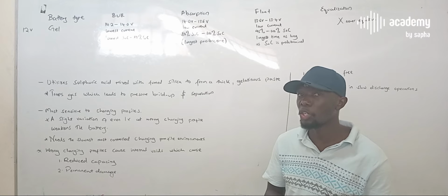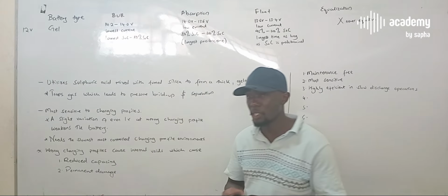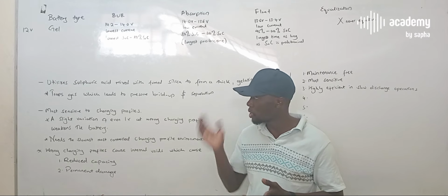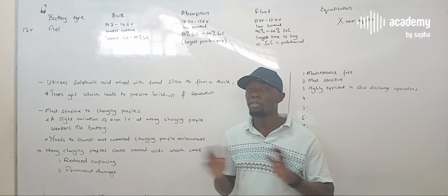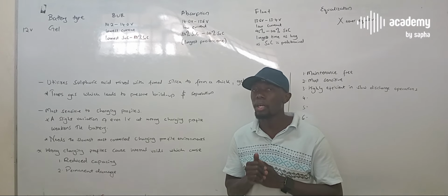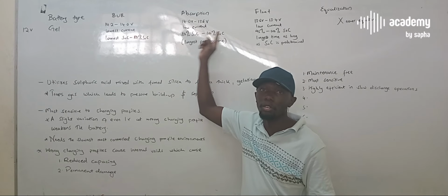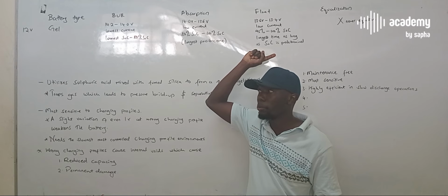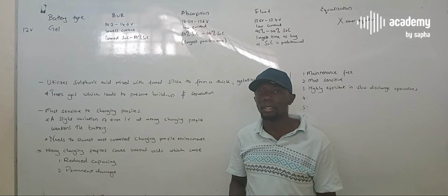But even before you get to installation, you should know that after sizing, when you now go into the market, just based on this information, you'll realize that some components will never be compatible. A gel battery will never be compatible with a charge controller that cannot understand this information and send voltages depending on the actual charging state that battery is in.